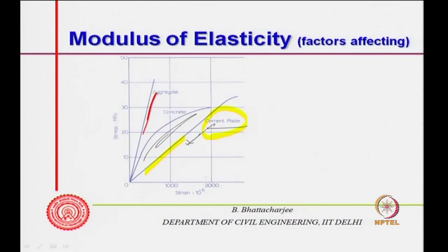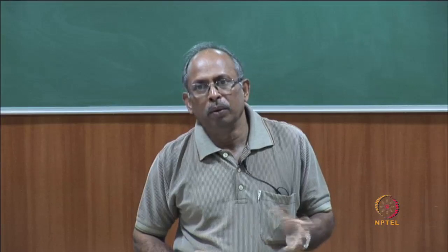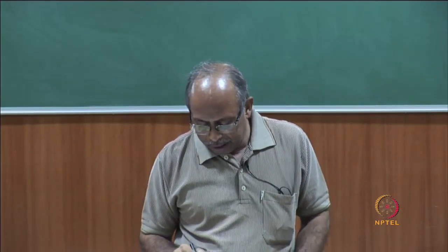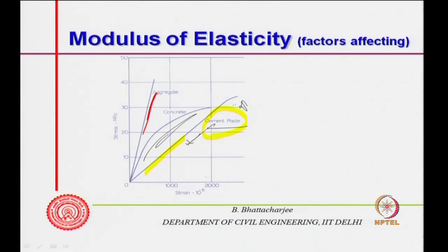The aggregate stress strain behavior is of course fixed, because you have taken the rock and the behavior will be fixed. Cement paste of course is under your control. So, if you improve the cement paste modulus of elasticity, the concrete modulus of elasticity also will increase.